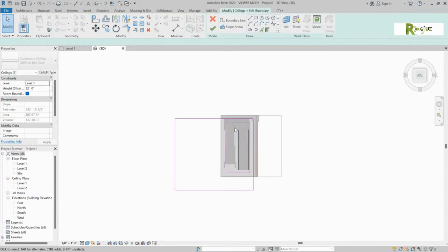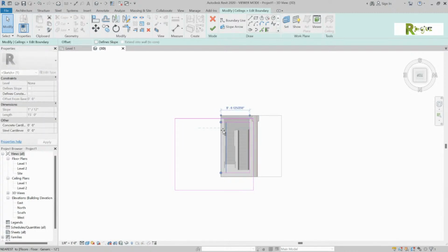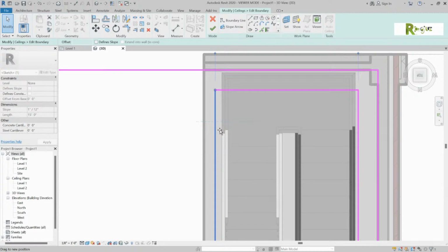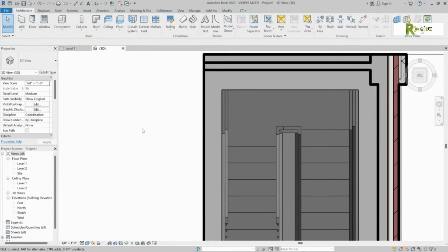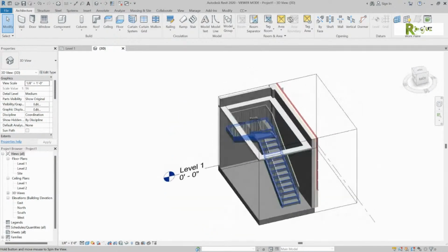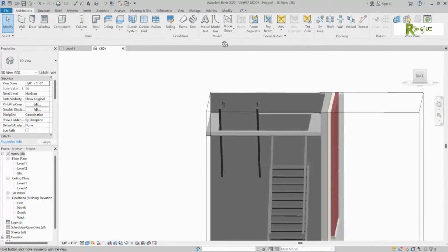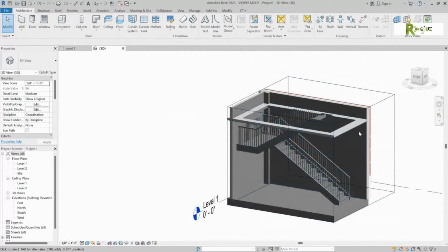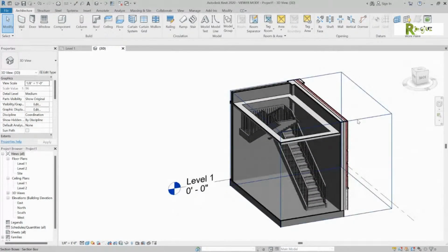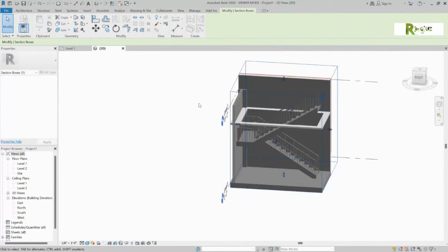That's it. Click on that wall and drag it. Click and drag. This is what you want to begin to feel with Revit. Now come back and you'll see it'll actually snap. Watch, it'll actually snap to that stringer. Keep coming till you see how it turns those things blue? It's telling you it's snapping to that edge. Snap to the outside edge of that stair. And now do your finish. Yep. And you'll see that now your stair is going exactly where that ceiling was. And it's real important that you learn to drive it like that video game and don't do everything with the trimming and trying to exactly measure. You want to let Revit sort of guide you into how to draw that thing correctly.